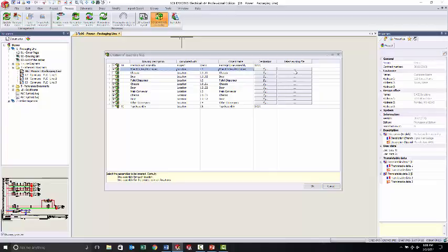So if you are routing a harness inside of a frame or inside of a cabinet, you can take their mechanical assembly, and that's where you will start out without having to go find it and insert it. It will automatically start there with that assembly and then build your electrical part subassembly in it. So this gives you some added functionality as well. And then, of course, it also gives you a destination if you are copying it into the project.